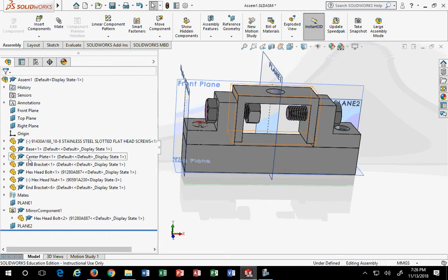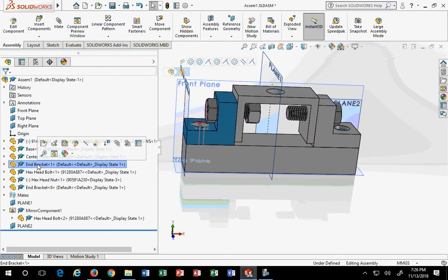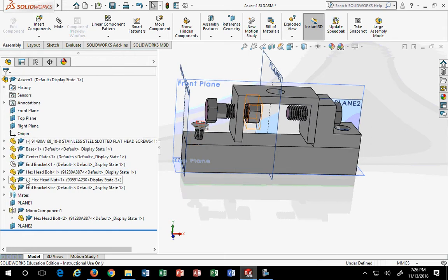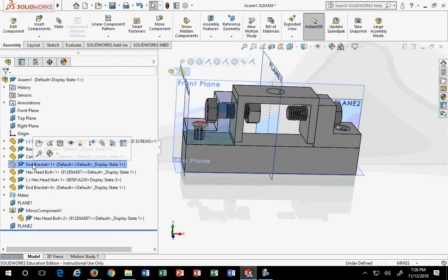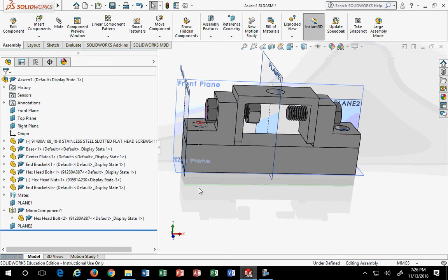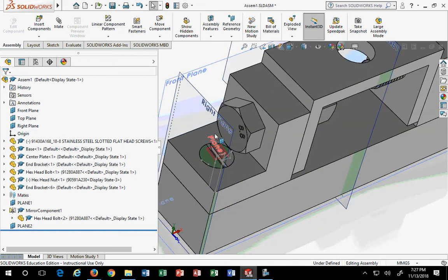Okay, watch. Click on the item in question. Hide component. Click on it. Show component. Got it? So if something quote unquote disappears, that's what you do. That's how you can find it. Relocate it. It didn't disappear. It's there. It's probably buried in a part.